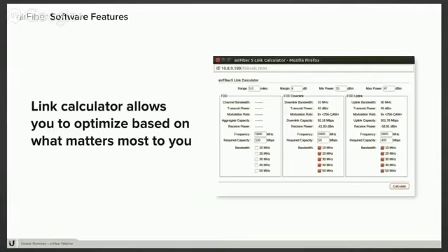And then this will go back and calculate for you what the ideal frequency, or not frequencies, would be. That would be nice, because frequency blending is somewhat complex, but we don't have that integrated yet. But it will let you know what the minimum bandwidth you can use is and at what power level you need to use it in order to get the required capacity through. And that also takes into account margin, the C to I, sensitivity of the radios, any sort of pre-distortions that we do in order to create the linearities needed for the transmit and receive. Just all sorts of characteristics. The entire radio model is actually integrated into this tool.